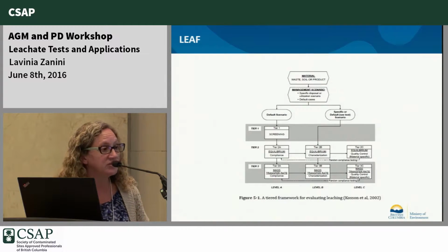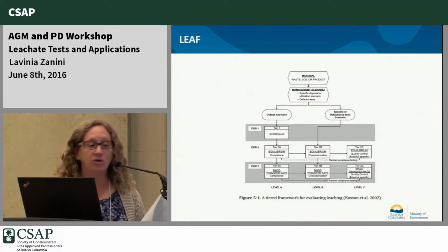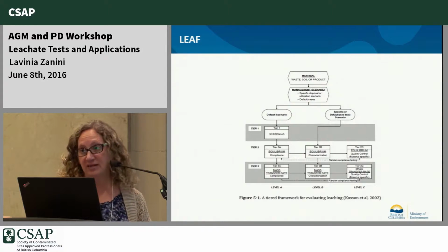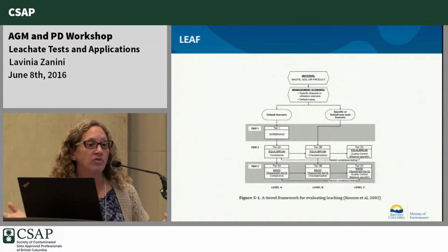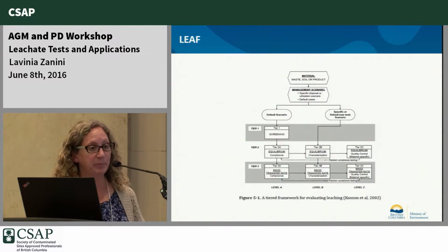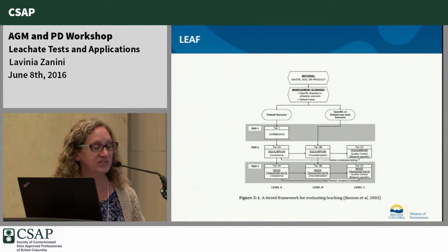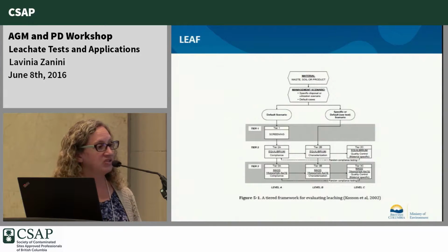But if you have more information on your site and you feel that Tier 1 is too conservative, you can go into Tier 2. That's where you use a different leaching test, and you can compare the two tests in order to get a less conservative number. The whole idea with the two tests is that the first test would demonstrate if all the contamination is available for dissolution.